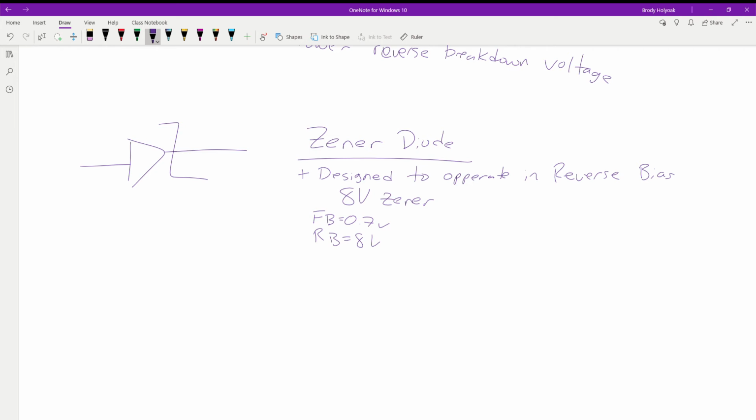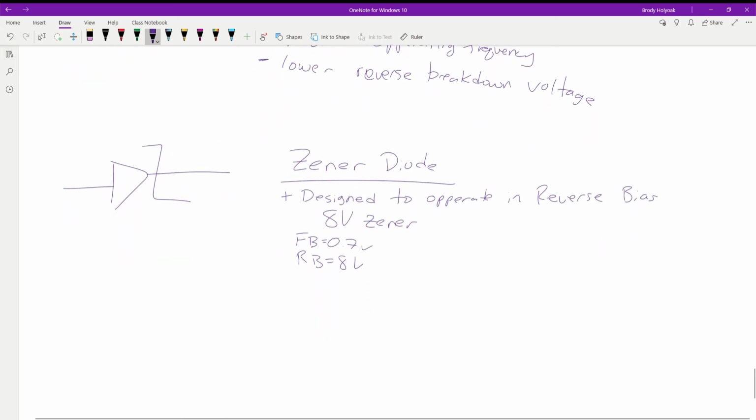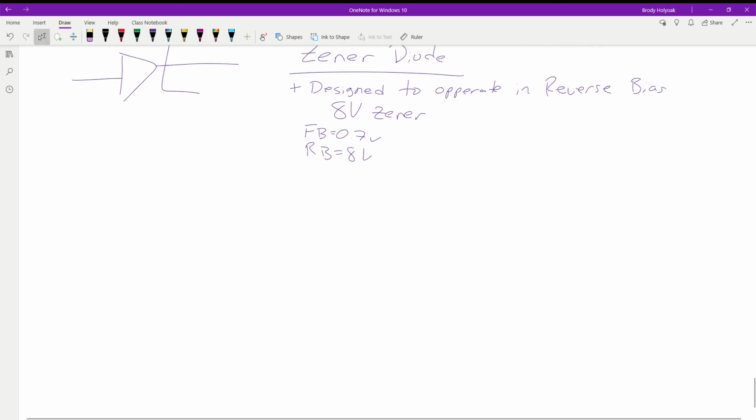It helps eliminate a lot of AC noise when the values are above the voltage. Because normally if you have any kind of power fluctuations, you would see them up on the high end, you would see a little bit of ripple in this. The Zener diode doesn't care once it gets over a certain threshold, so even if it's doing this, this is our threshold, you're going to have flat power. So it's one of the first steps to regulating power, is it maintains this voltage. Doesn't care what happens above it.